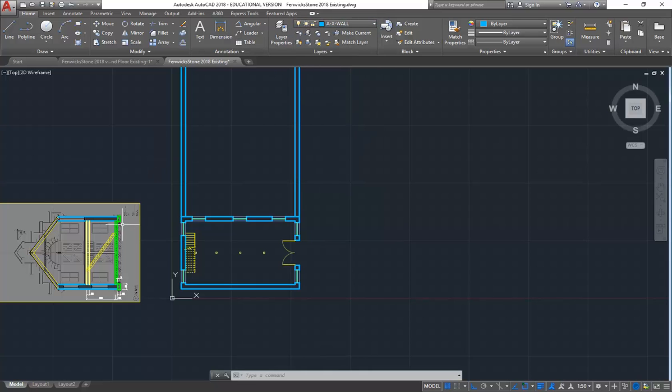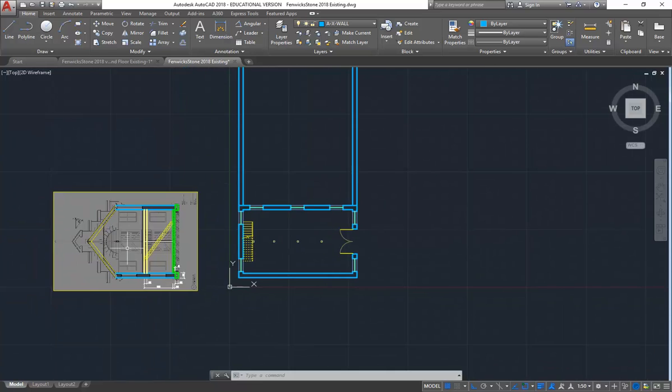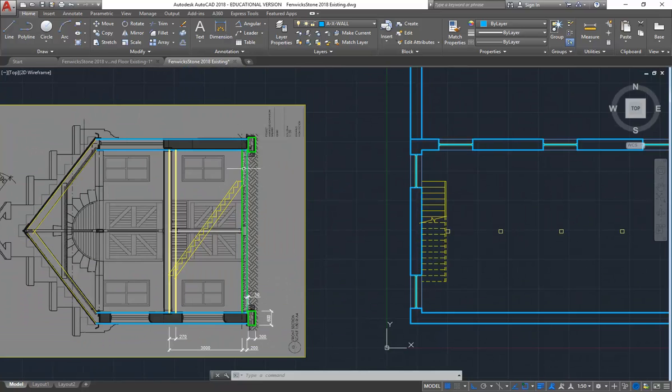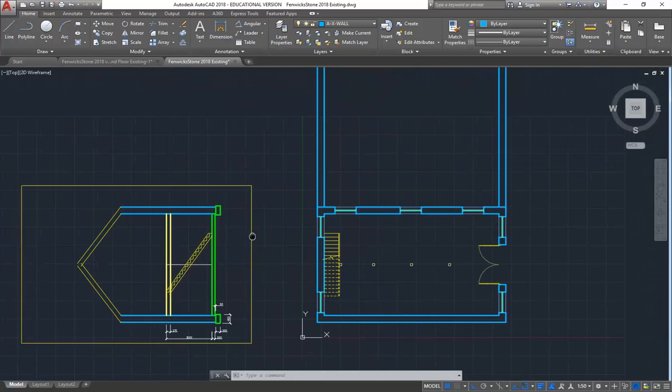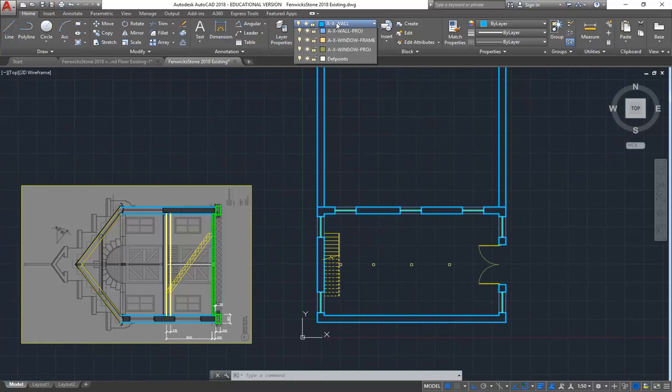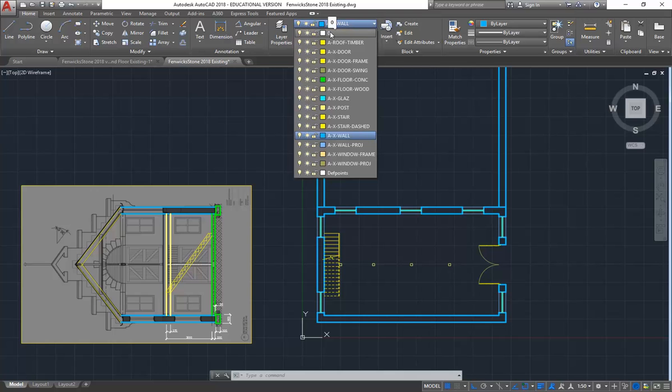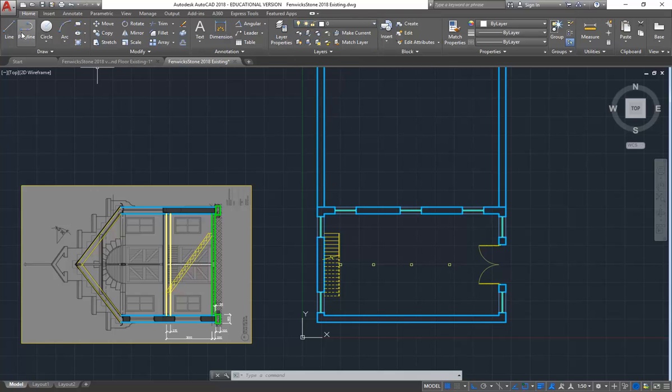Will come next, but what I want to do now is get the line from my floor to line up with the line for the floor that I've drawn in my other section. So this is the real trick. I'm going to draw, maybe just on layer 0, a new line with ortho turned off and polar turned on instead. So polar there has the option to set the angles to, let's say 15, which gives me increments that will add up to 45.